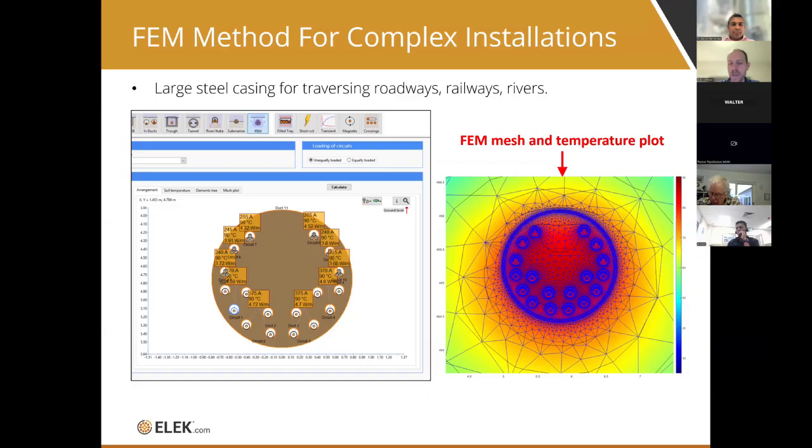I think we can deal with any number of ducts inside pipes, right, Edston? Yes, that is. Now we can do multiple circuits inside the duct, which we're going to explain and show you in an example. There's no limitation, right? Yes. So this is basically multiple casings and also multiple circuits in a duct. Yeah, that's where the pipe type cables and river crossings come into play. Very complex air convection models have to be modeled inside these casings. I think Michael, who's also part of our team on the call, is well versed in these calcs as well as Edston.